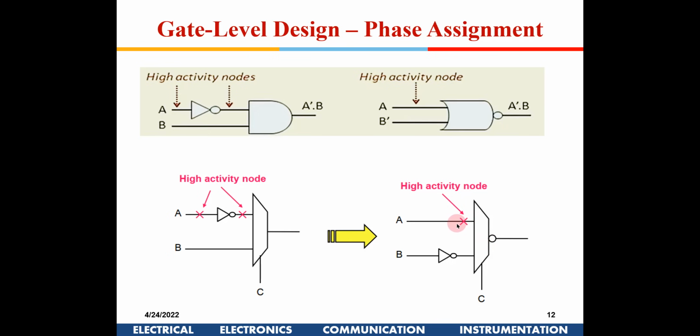That NMOS will be off, right? Is it okay, Dilshan? A mux is nothing but gates. If most of the time B is to be routed here, then that gate will be kept off. So whenever A makes a transition, because you have a transmission gate, that will just block A, so that's not going to affect my inverter.